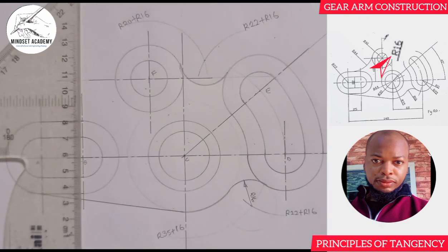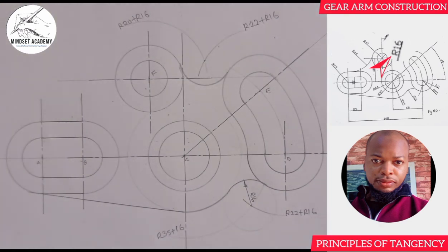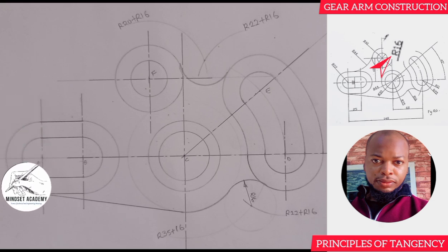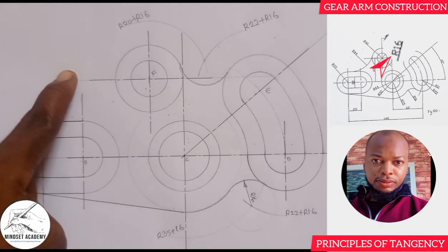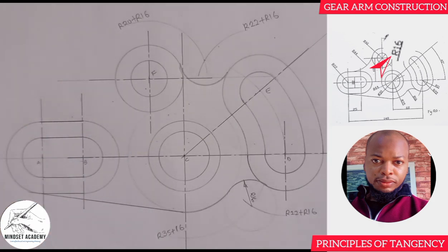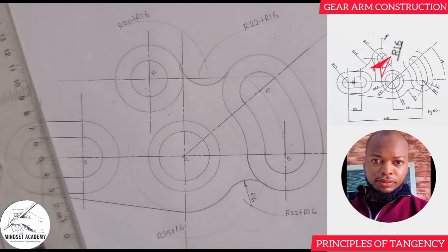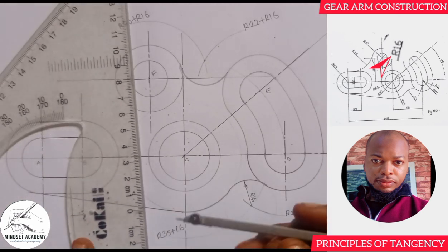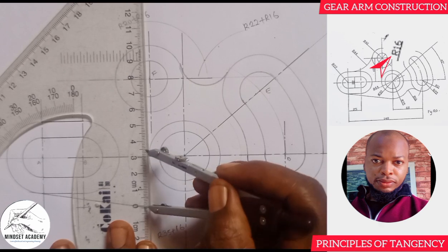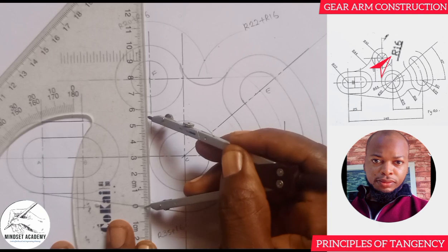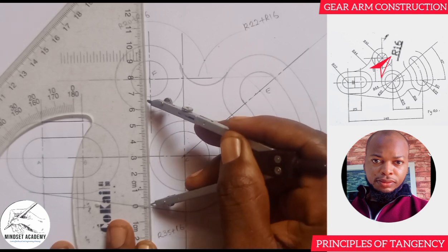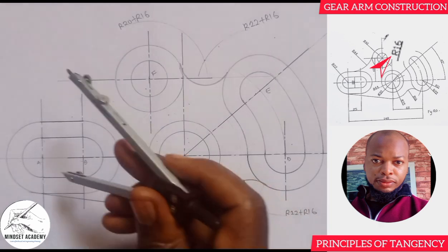Can you see that? Now we move forward to the next one. When you look at this, there's another one that is coming in here also, right? And it's going in, so it will be the radius of this 22 here plus the radius of 44. Since it's going in, it's external. So 22 plus 44, that'll give us 66. So you're going to measure 66 on your meter rule. From 0, this is 66 here. Then I'll place it here.